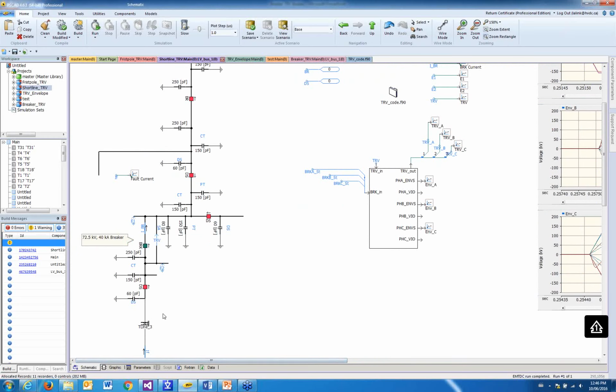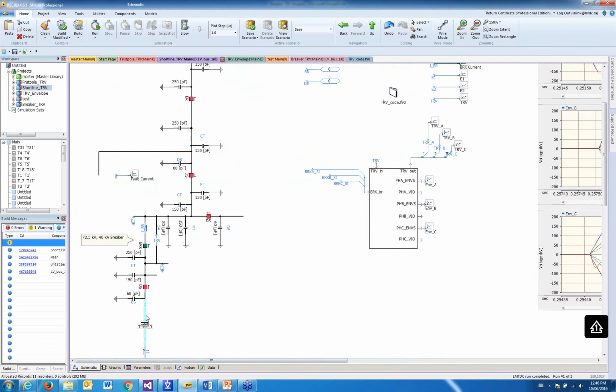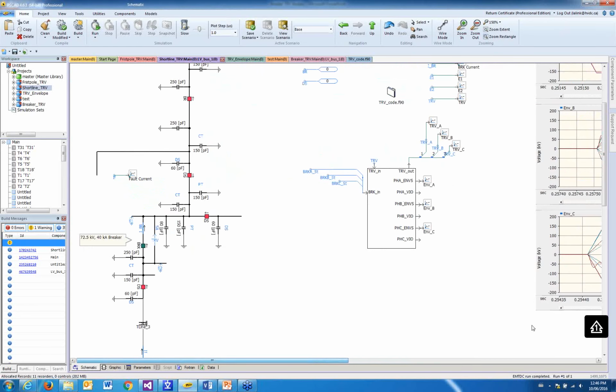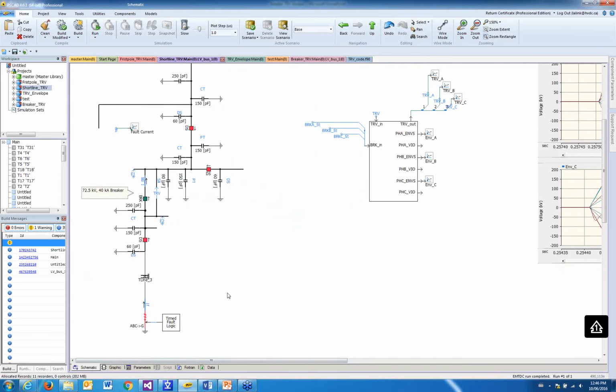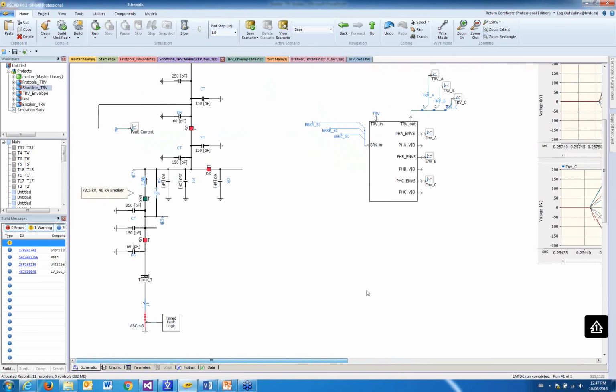Short line faults can create a significant effect on the initial TRV, as you see here, because of the very high frequency sawtooth type of voltage you observe from the transmission line side. As you see here, this is a bit of an exaggerated sample. You see violation for all the waveforms, but in real life it may not be. The main point here is to demonstrate the sawtooth nature of the resultant TRV.